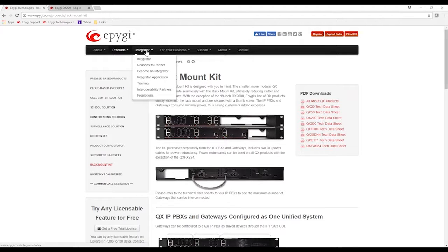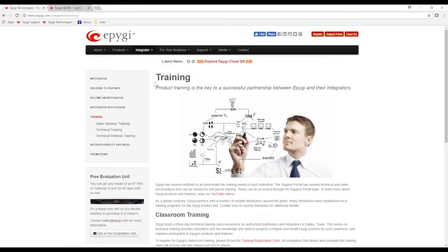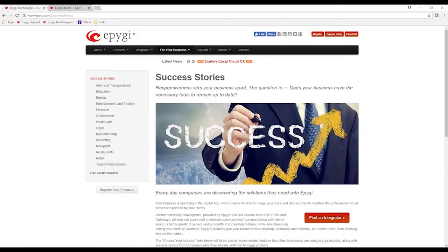Okay, with the rack mount enclosure, it also comes with this. You can see this gray satin cable, DC cable. You can tie 2 units together so that one unit can power the adjacent unit. It also lends itself to some power redundancy, so you can power both units from a separate power source, different backup power supply. If one power supply fails, then the second unit would be powered by the first unit.